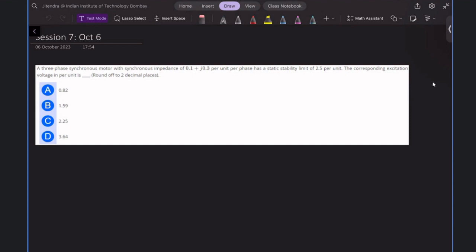Armature winding is responsible for your output power. However, in certain cases, to compensate flux, if your field is not capable enough to produce rated flux, in such cases, armature winding can produce a magnetizing or demagnetizing component.